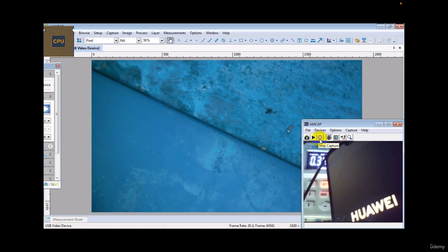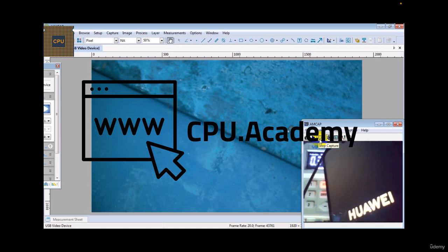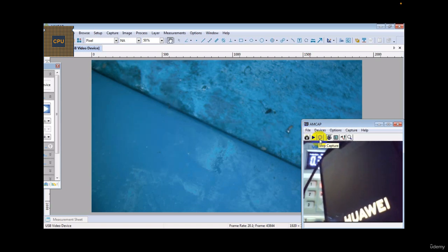If the software didn't work, we are going to do a reballing hardware to the NAND. This is exactly how we will work on all power issues. We need to determine, is it IC power problem or CPU or NAND? If it is an IC power problem, the power supply will show less than 0.1, less than 100 milliampere, so we will work directly on the IC power, as we will see here.